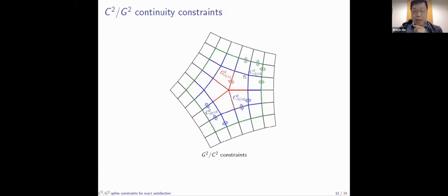Finally, with this kind of construction, all the basis functions for each of the control points, as you see, are similar to any other subdivision scheme. Each of the basis functions will be constructed as a piecewise polynomial basis. So that's what we have here.